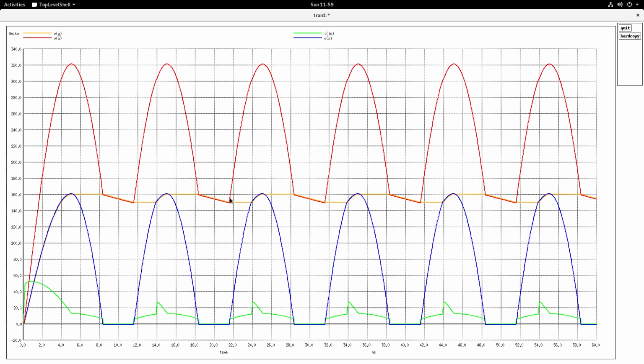This is generally not a problem, because the output of this is generally given to DC-DC converters or DC-AC inverters, and they have very good closed loop control mechanisms which will handle fluctuations in the DC link as provided by this power factor improvement circuit. So this very high ripple is generally not a problem, but that is a disadvantage of this particular circuit.